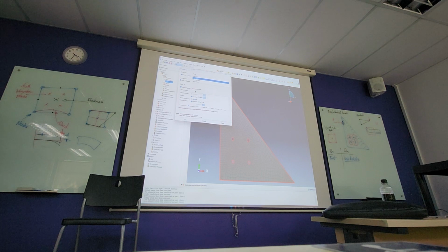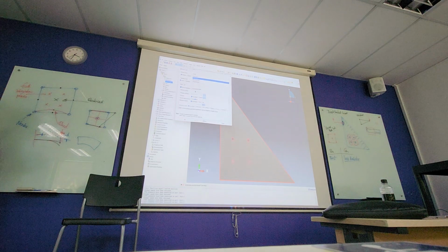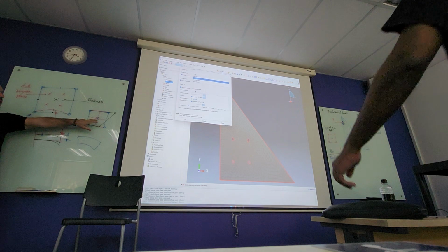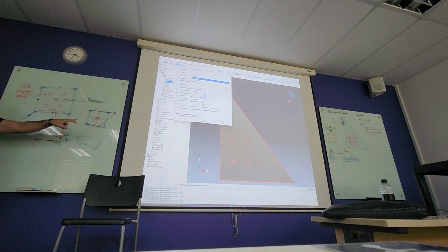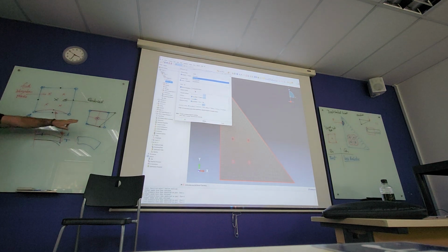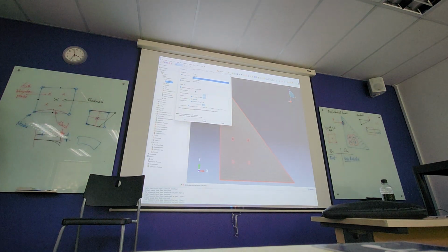So that's how that element deforms, because edges, sides, they cannot curve. What then happens is that due to that deformation, because you got only one point at which stresses and strains are calculated, this element is not able to pick up this deformation. So although the element deforms, because you got too few integration points, it's not possible for this element to identify deformation.